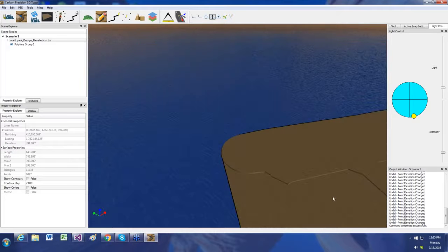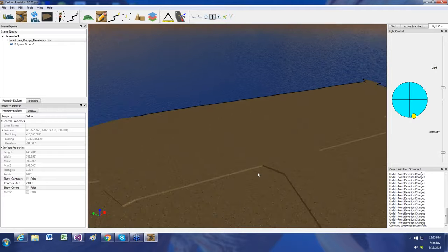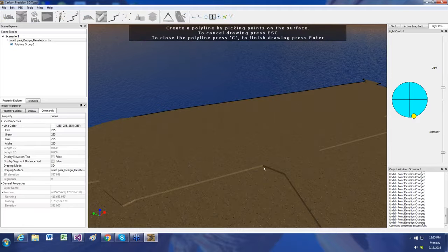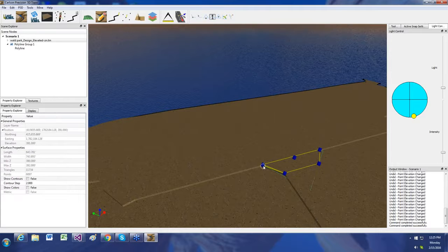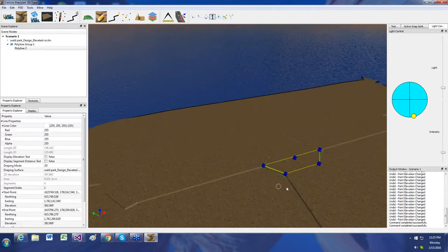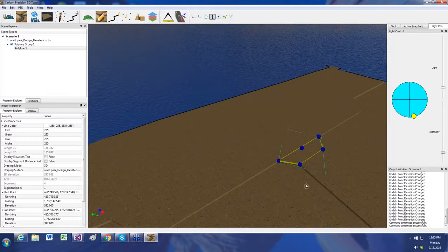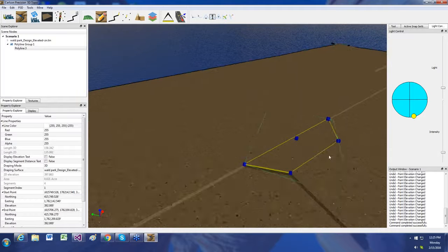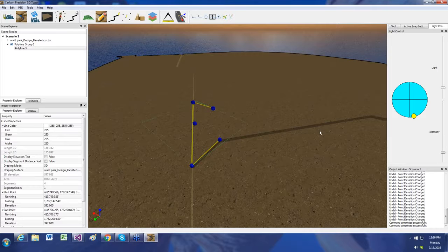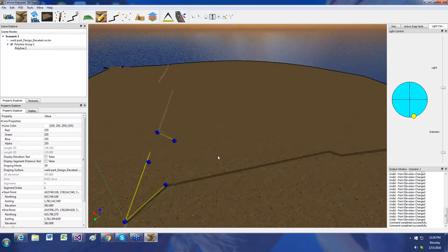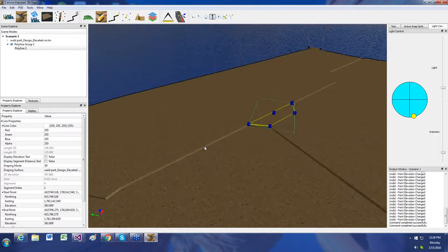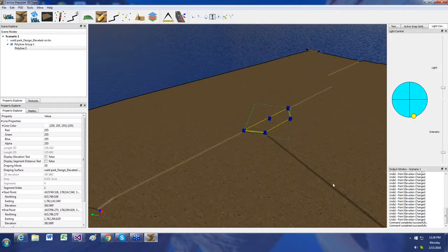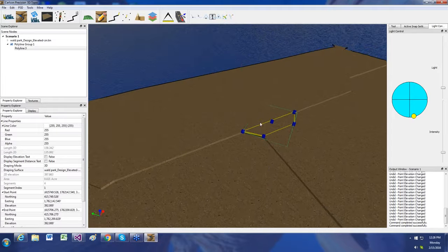So now that I've got that cleaned up, I'm going to show you auto texture really quick and a way that you can control auto texture. So I'm going to draw another polyline just for construction. Since auto texture really follows these flat surfaces the same way, I want to make this asphaltic, but if we look at the surface, this is another continuous, it has the same continuous slope. So if I didn't put some control in here, I would get asphalt all the way out to here, and I know that this really should be rock chip area.